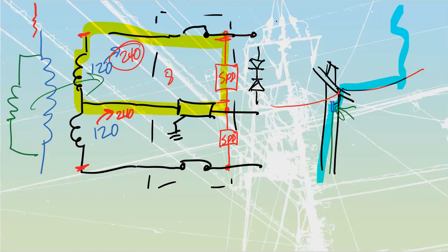What they will do with the MOVs is they are going to be similar to a Zener in that they'll maintain a voltage across it. So they are going to do clamping for us. Clamping is different than diversion. Remember that my thyristor is going to drop my value of voltage. Anything that clamps is going to just chop off the top of a bad waveform, and it is going to clamp or hold that voltage level. If we are looking for 120, it is going to hold 120. The waveform might be distorted, but it's going to keep the voltage level correct.